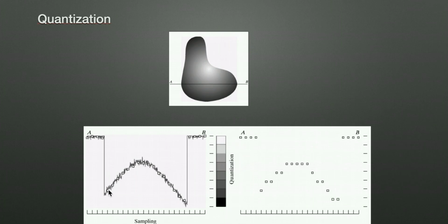That is, let's say this value is an approximation of this entire range. So this is a particular range that you have. Any value that falls in this range, suppose you have chosen this sampling point, it maps to this particular quantization value. Even if you had a sampling point like this, it still maps to somewhere over here, the upper limit, but it still maps to this particular range of values.